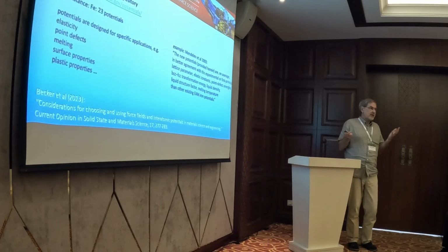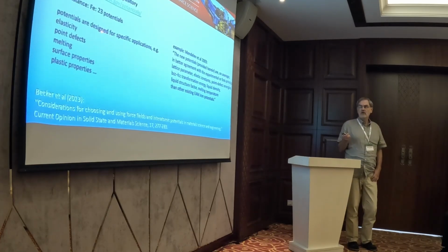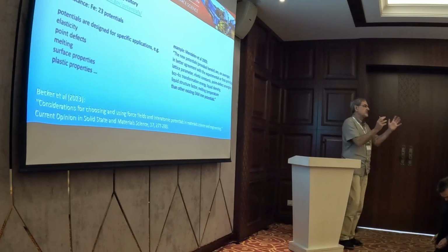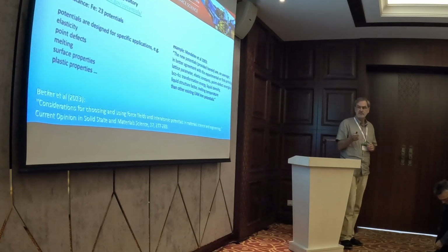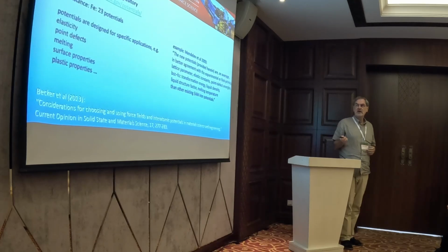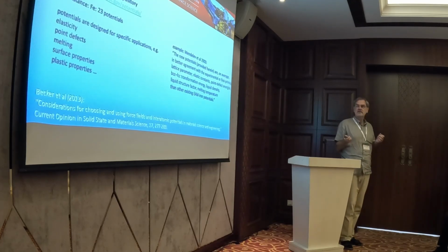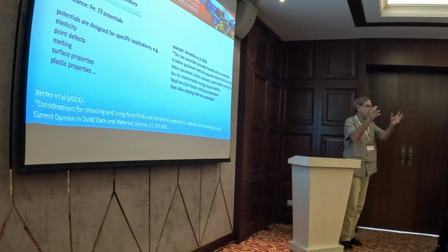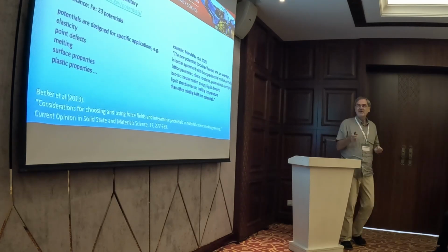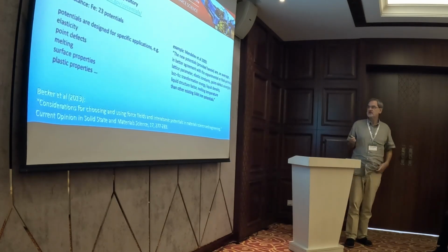And then which potential to choose? Each potential has been designed with a particular application in mind. So some are good for melting, others are good for surface properties, others are good for plastic properties. You have to think of what is your problem, which properties should be represented best in your potential.